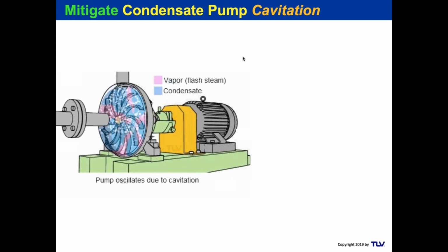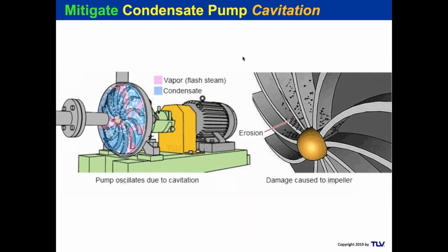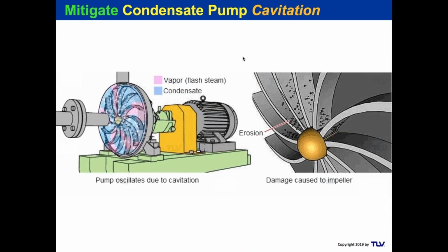The vapor pressure is higher, and that means that it is going to turn into steam as soon as you get a dynamic change. So when you spin that impeller, the velocity goes up, the dynamic goes up, the static pressure goes down, and you get an expansion of some of the water droplets in the vapor because of the drop in pressure. But because there's water all around it, the water is a heat sink, and it causes those steam droplets that just expanded to go back down and form water again. You call that cavitation. That's why the impellers look like that, or we have different vanes pulled off of an impeller.